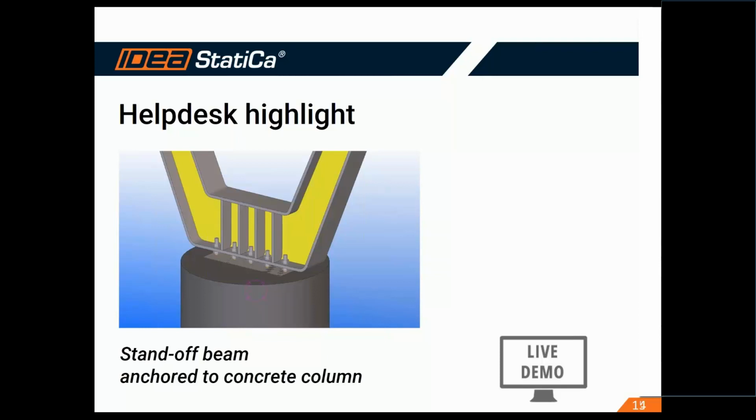As you can see in this example, it is a standoff beam, so it means that the beam is not directly welded to the base plate, but it has an offset from the base plate. So this is also a feature that we can model in IDEA StatiCa. So let's switch back to Kostis, who is going to show you exactly how we can model this type of connection.